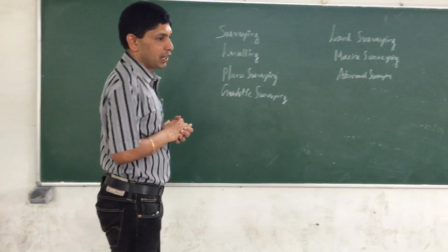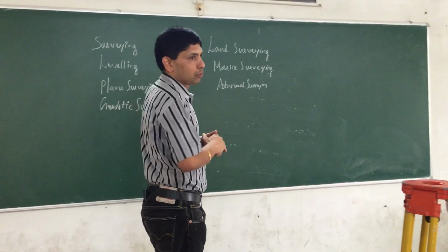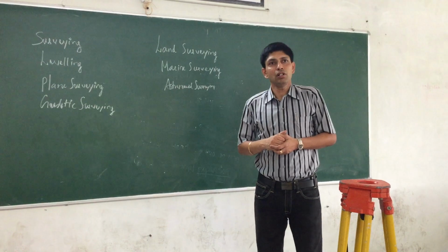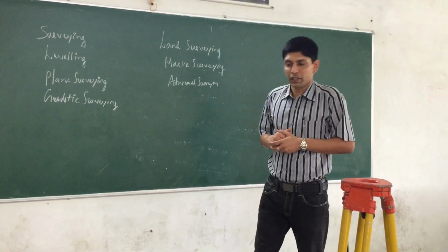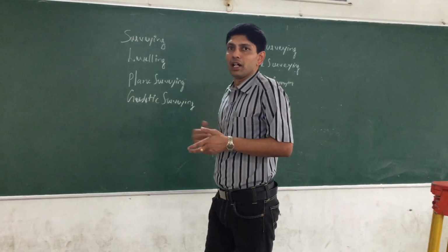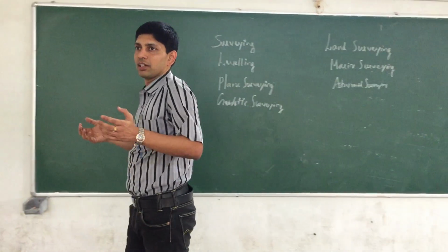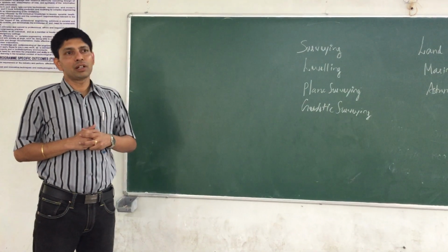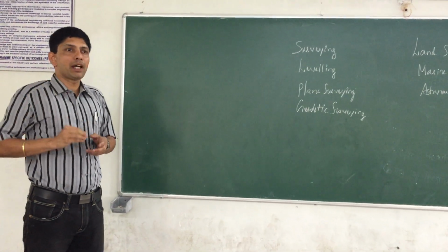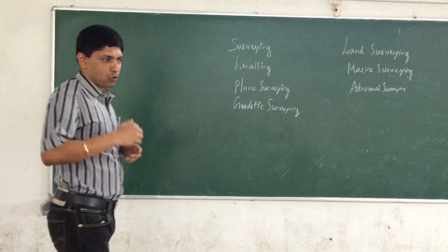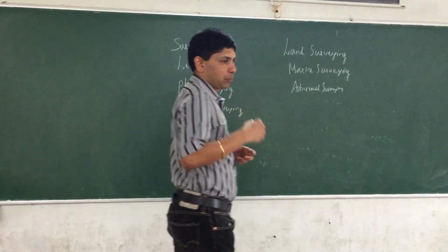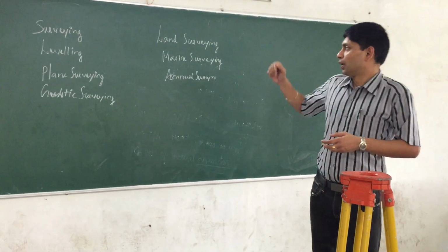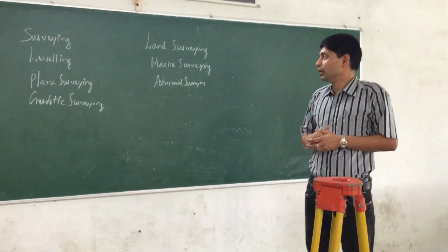For a residential land area, we will be using normal chains, normal theodolites, etc. But if you go for very big industries, we will be going for advanced tools such as total station or digital leveling, etc. And here, if you see this particular land surveying, it will be carried out mostly by a group of people, minimum, depending upon the amount and extent of the area, the number of laborers deployed will vary.